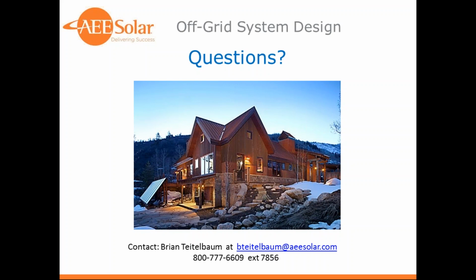Yeah, we can design for 50 amp, but we're going to end up with a system that's probably a lot larger and a lot more expensive than you actually use. So looking at actual usage and not the rating of the input is important from a cost perspective, and also a space perspective. Obviously, huge arrays or huge battery banks take up more space. So we really want to look at the loads and not just what the source is.